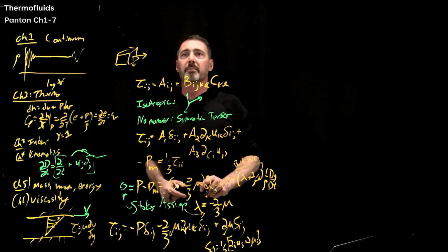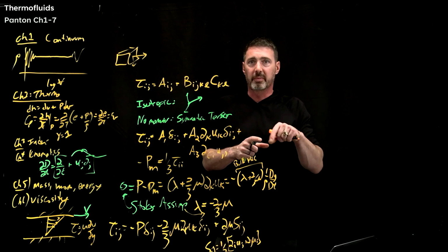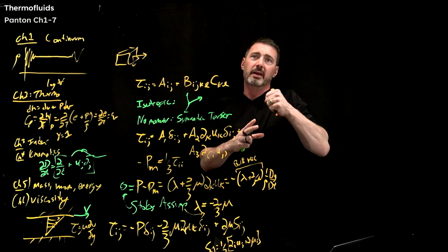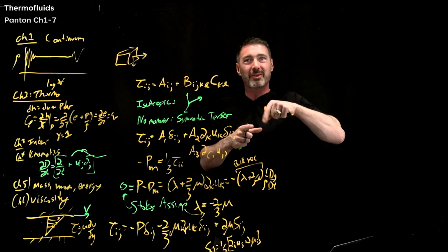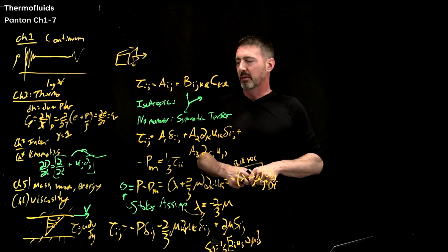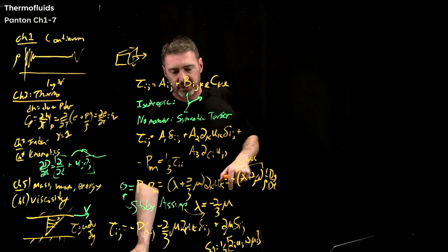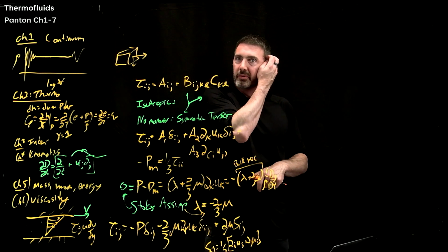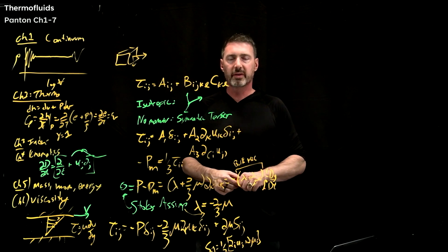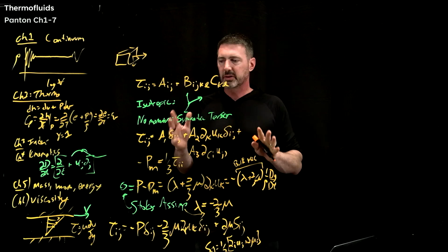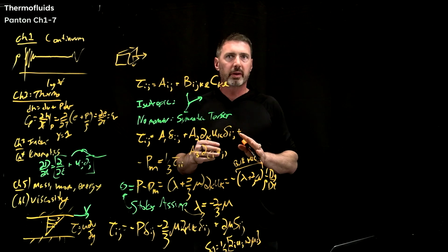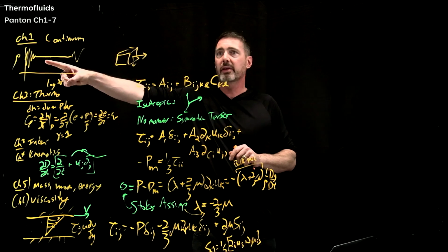okay, and it's linear, and so actually viscosities a lot of times are basically measured by that. Usually it's a disk with a really thin annulus, and you're measuring the torque that you have to apply to spin that at a certain rotation rate. So you can back this out. But that gives you this. And so a lot of times you got to be careful. People would say it doesn't necessarily give you all the viscosity, but it works pretty well for incompressible, and these assumptions are not bad. Okay. Again, there are other really weird problems that can show up in rarefied gases over here.